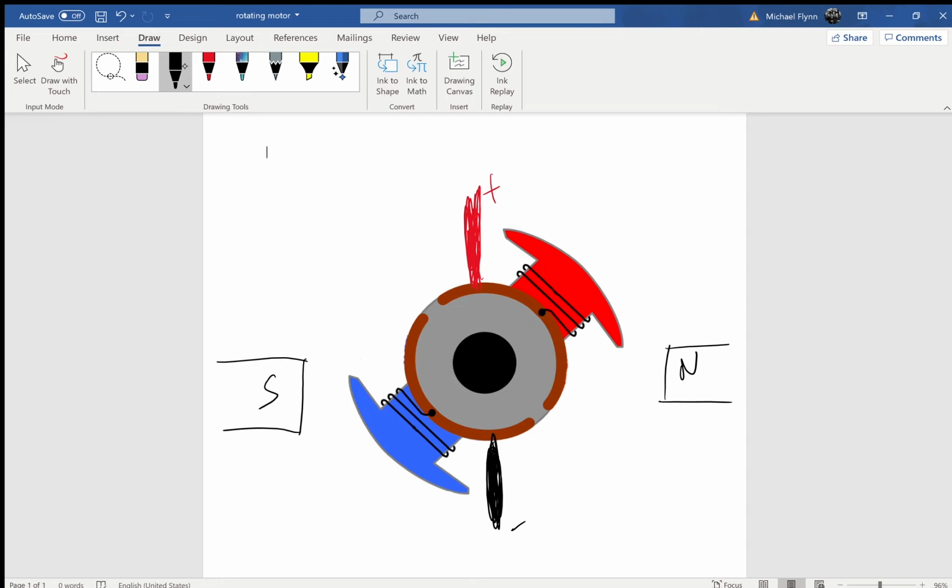There's a split ring that's colored brown in here. That's on this rotating armature. So there's a split ring on this gray rotating cylinder in the middle. And then there's this blue armature on this side and a red armature on the other side. The colors are irrelevant, but for the blue, there's a coil wrapped around it, and that coil continues, and it actually is part of the same coil that's wrapped around. You just don't see all the windings, but it's wrapped in there somehow.